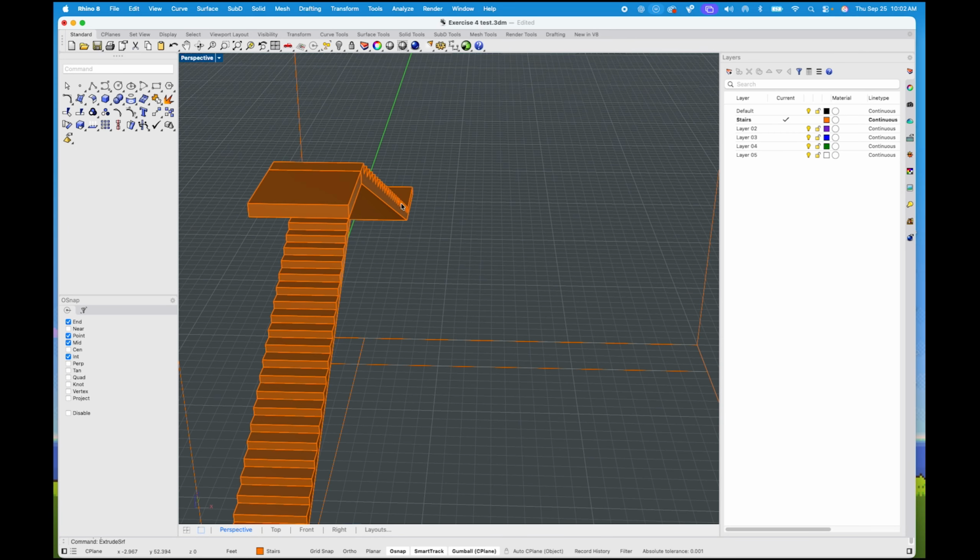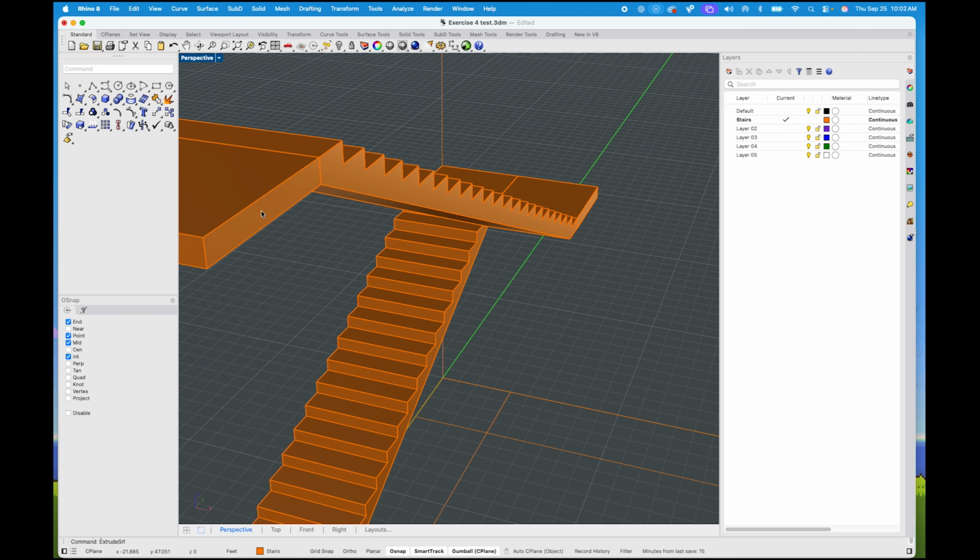Now let's maybe talk about a ramp, because we do need to calculate that a little bit. And to be fair, if I go 12 feet, how many feet do I need to go up? 1, because that would be a 12-to-1 ratio. If I go 24 feet, how many feet do I need to go up for a ramp? 2, right? Because that would still be a 1-to-12 ratio, right? And here's what I mean by that.